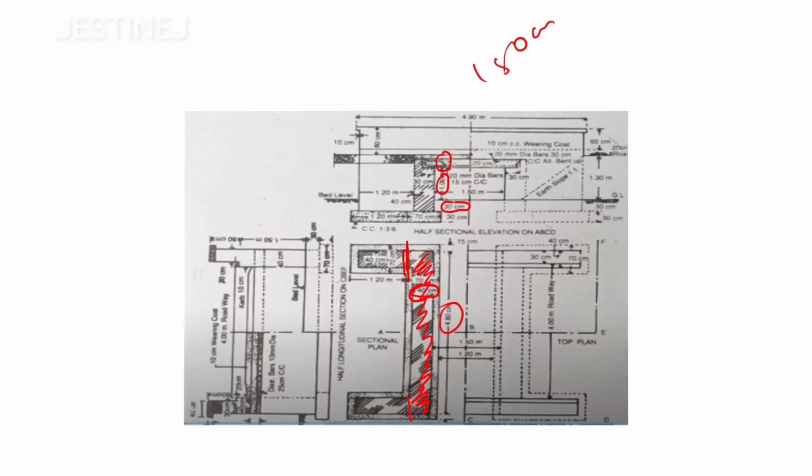And if you observe the case of these wing walls, this dimension has to start from here, up to here it is going to be 1.2. Here also some portions are there. If you consider these portions, the distance is 1.2 itself, and this dimension is going to be 0.4. So these wing walls are 4 numbers, and abutments are 2 numbers.